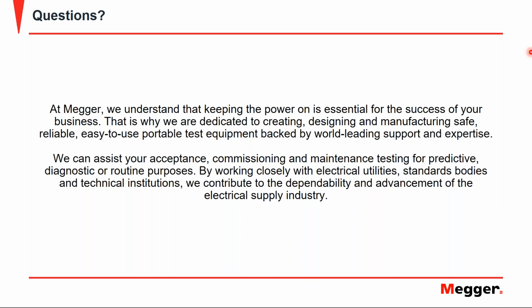All right, Charles, thanks. I think we've got one more question I can send over to Hein for now. For example, in TDM 4540, without any load connection on it, how do we know if the test set high voltage cable itself is free of partial discharge?